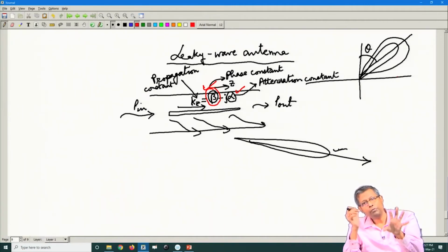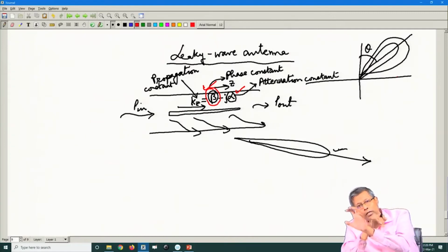So, which part of the circuit is responsible for the coupling? If I can express the physical geometry of the antenna by means of an equivalent circuit, I can try to isolate certain elements of the circuit which are responsible for the coupling to the antenna, and certain elements of the circuit which are responsible for generating particular resonances.